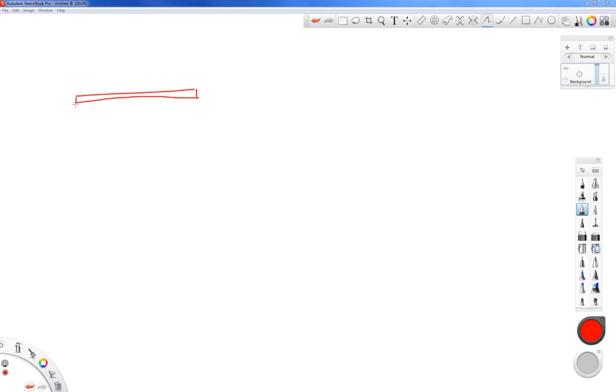All right, so to kind of review a little bit, here's a beam, and if the load happens to be discontinuous, such as in this case with a simply supported beam, what you have to do is break this beam up into 2 regions. Sometimes this is in the middle of the beam, sometimes it's in different spots.